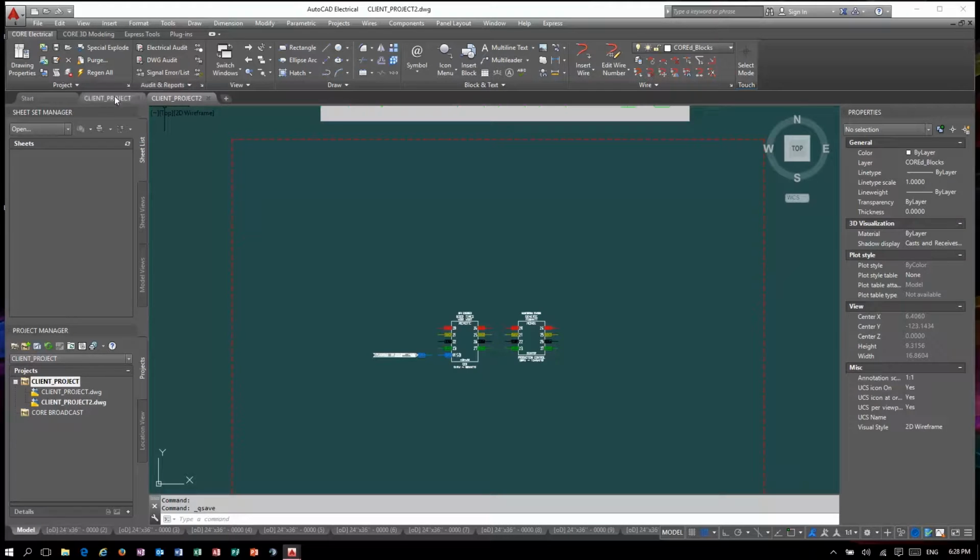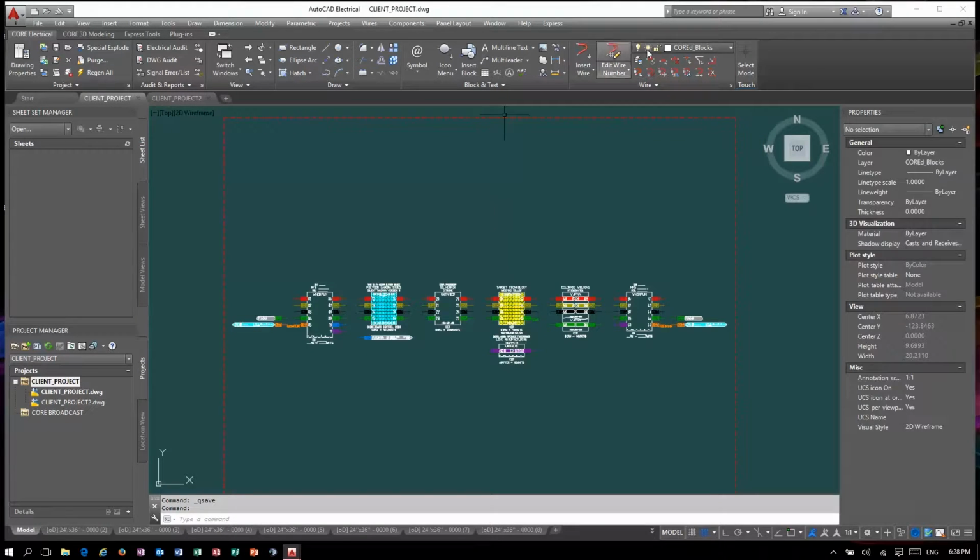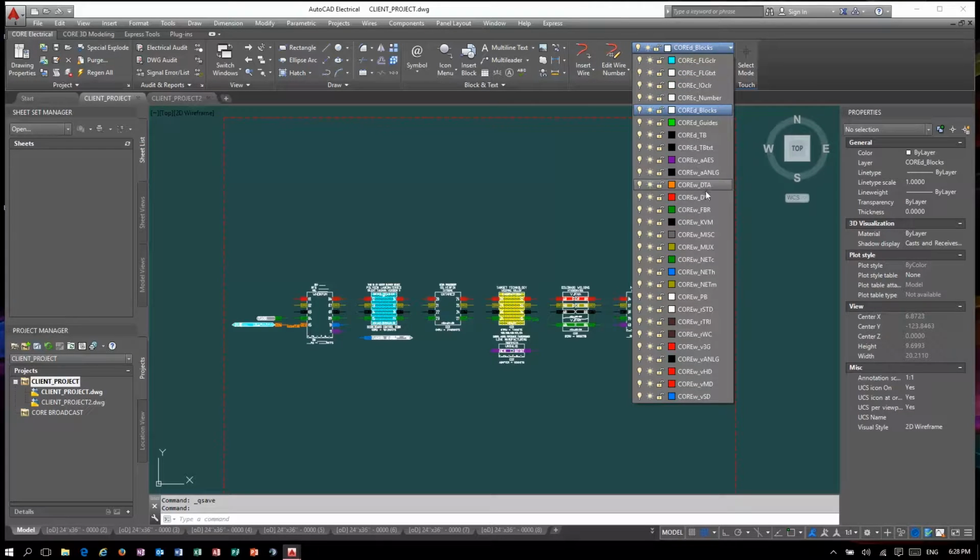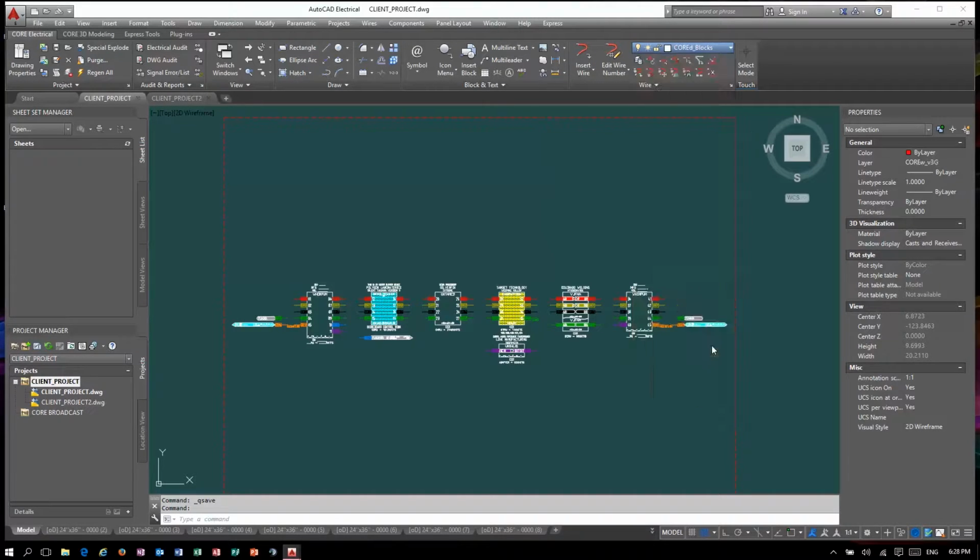Now that our equipment blocks are in place, it's time to wire the devices. Before physically attaching the devices, it's important to select the wire layer associated with the signal or connector used, to allow global updating of attributes and colors based on your in-house standards.